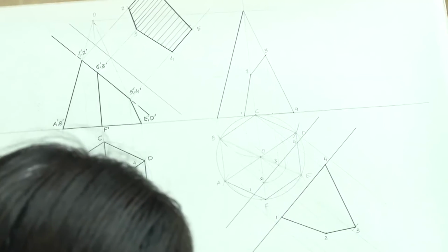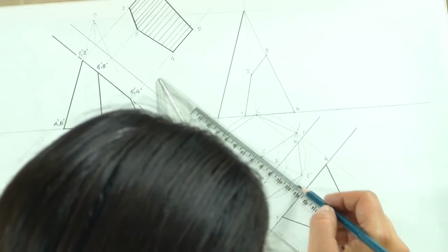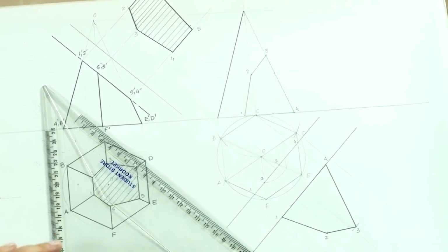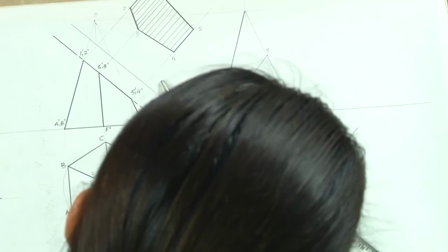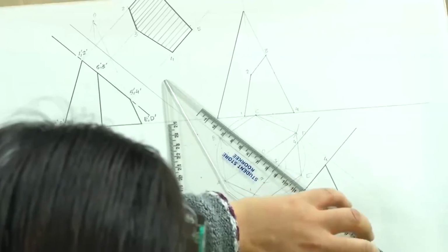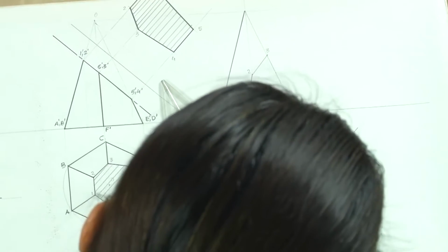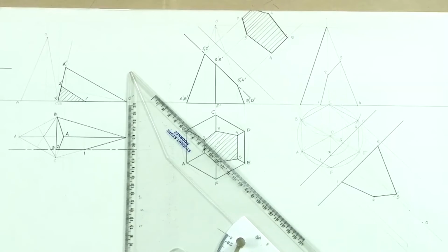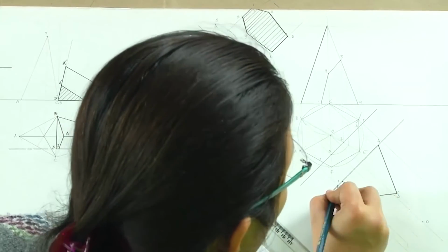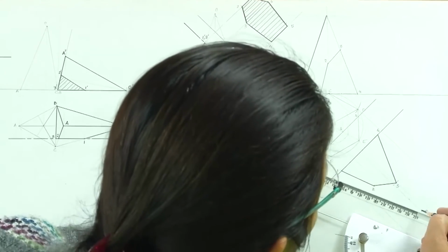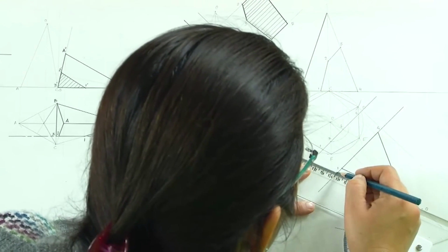So, we have this B, we have the A. So, A is here, and what we are going to take is this O, which is equal to the height of the pyramid. So, let us measure 8 centimeters here, which is what the height of the pyramid was, if I remember correctly. No, it was 10 centimeters. So, let us take 10 centimeters on this projection line for O. This is where your O is going to come, which is the apex, right. So, what we have now is we have OA. Let us lightly join and then you will be able to understand.